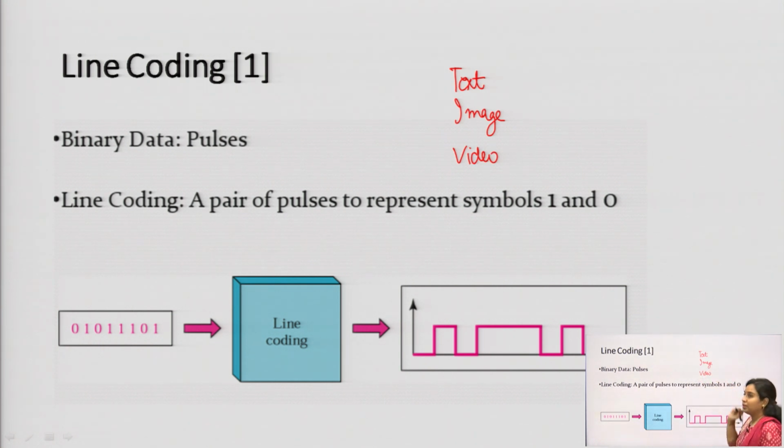So, this is basically the raw information you want to transmit and this is in the form of analog, but we want to convert this analog information into the digital. Why we want to convert this analog into digital? Because for converting it into digital, it can be stored, it will be more immune to noise, the digital signal is more immune to noise, and for converting this signal from analog to digital, we require an ADC. This is ADC, that is analog to digital converter.